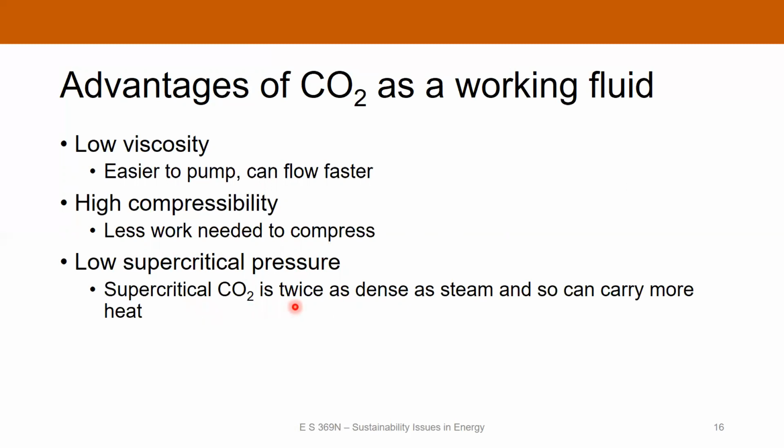And what this means is that supercritical CO2 is twice as dense as steam. And so it can carry a lot more heat just because the product of the density times the specific heat capacity gives you a lot of heat carrying capability. So there's a lot of people looking into using CO2 as a working fluid. It's pretty promising, and we'll see where these things go over the next few years.